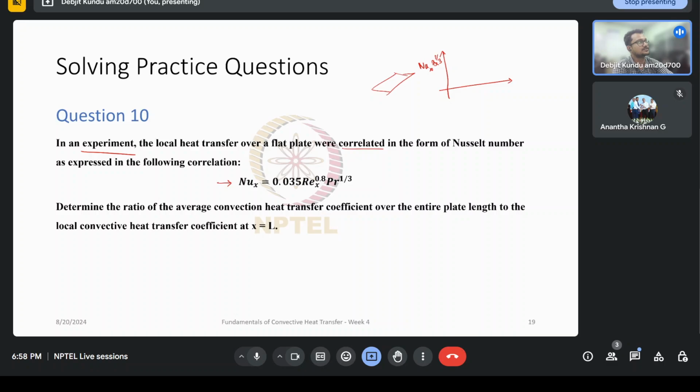Prandtl number is just a constant that I'm multiplying. And on the x-axis, if I have Reynolds number, let's say. And these were all done on a log-log scale. So I had log Rex and log of this. And I got multiple data points because the experiments were repeated multiple times. And using a fit of this data, I get that the slope is 0.8.